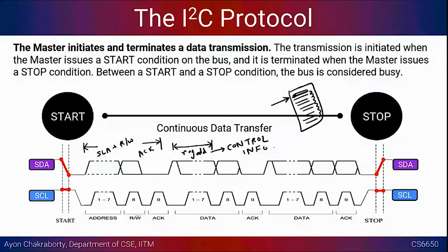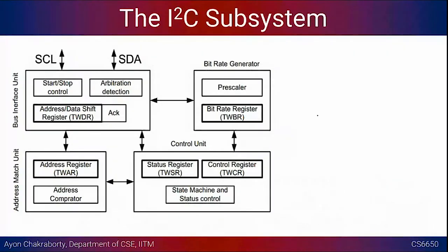So there can be miscellaneous configurations that you can do. Okay, so this all depends on that particular sensor. That has nothing to do with the I2C bus or this protocol. So after your SLA, RW, and the ACK is sent, it is up to you how you want to negotiate the data between the microcontroller and the sensor. Okay, so that is the application level logic.